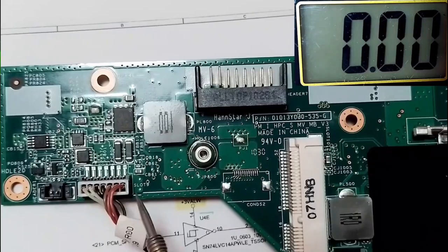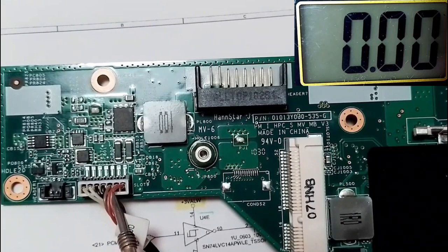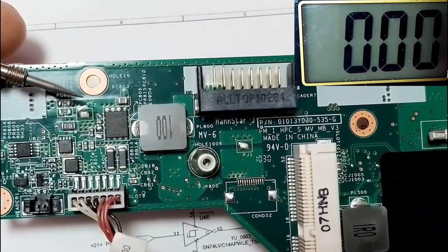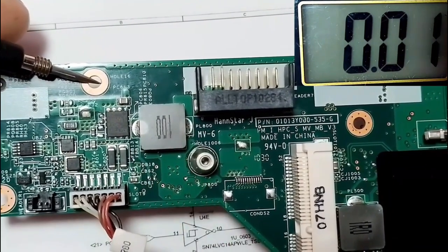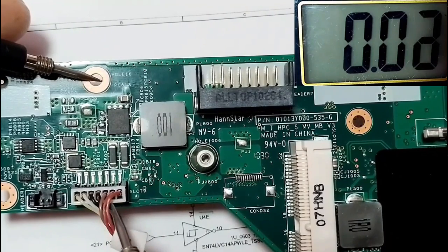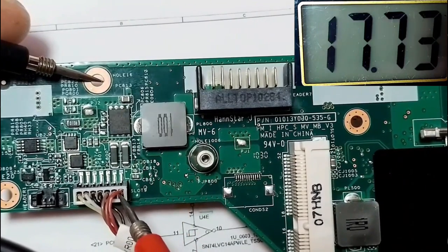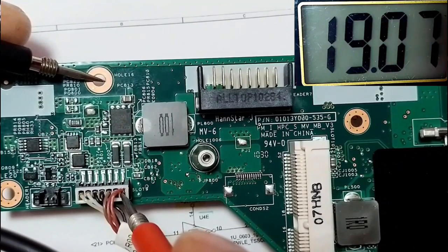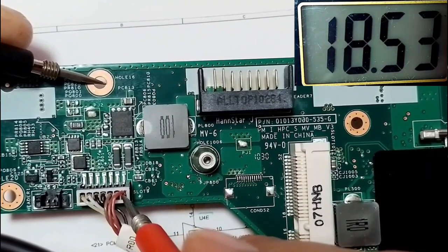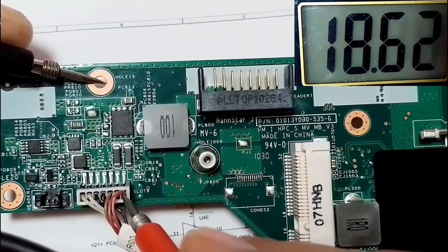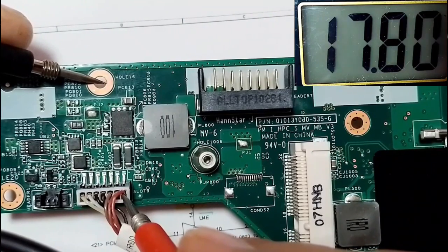So basically this is the power jack cable. Here these two red cables mean 19 volts, the positive side, and here we have the ground. So if we measure between ground, as you can see here, and these two red cables or these two terminals, we should get 19 volts on the multimeter. So let's check. Do you see? The voltage is not stable. We have 19, then 18, 17, 16.